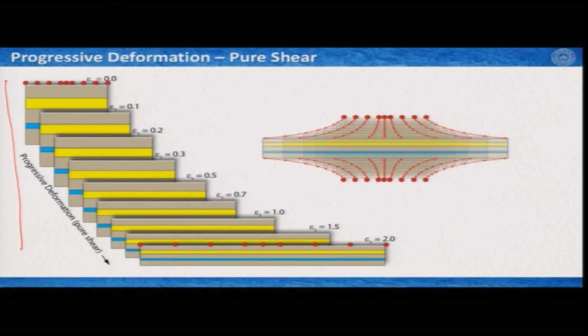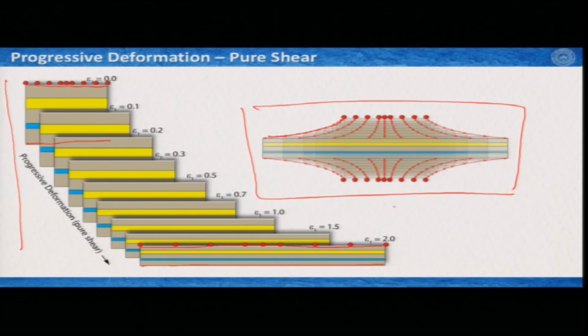Now, if I club all these images together, they would appear something like that, and I try to track these little red points in the form of particle paths, then this point would move to here and then so on. So, characteristically all these points, at least from the two sides, the top side and the bottom side, and how they have arrived at their end deformed shape, if we track each and every instance of deformation, then the characteristic flow path would be like this, what you see here in this diagram by red arrows. So, tiny red arrowheads, and finally you achieve a pattern. We will analyze this later.